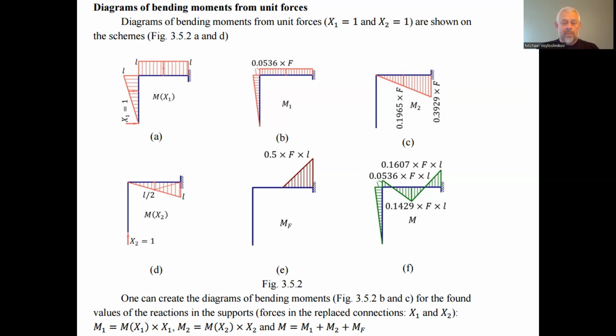We can use the previously obtained diagrams of the bending moments in the elements and segments of the main system, obtained by cutting the supporting links at point B. These are the bending moment diagrams of the unit forces indicated here in figure 3.5.2 A and D.